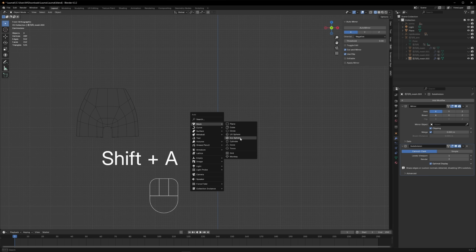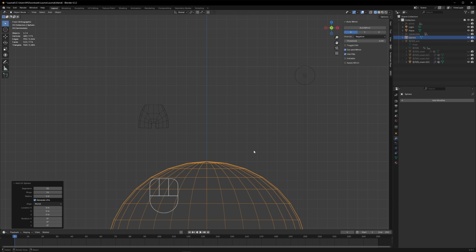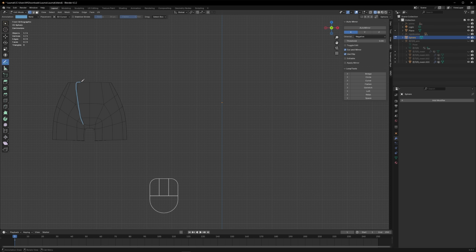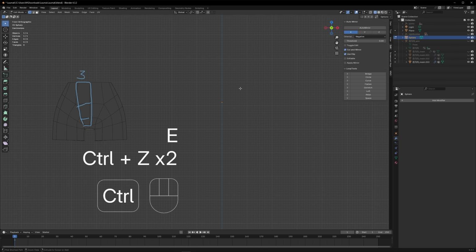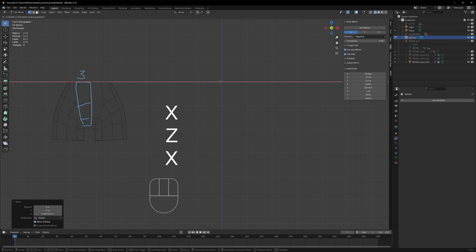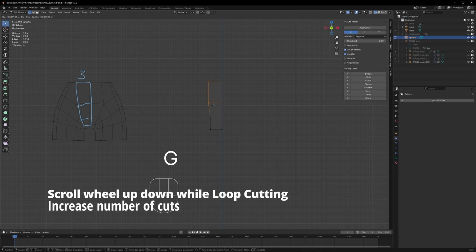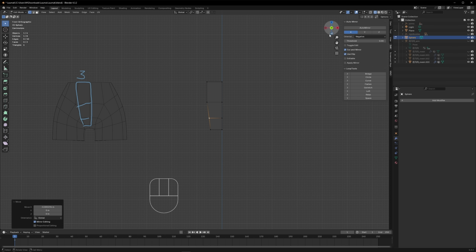Let's recreate this. Whenever I do a recreation, I break down the mesh into simple shapes and model the obvious parts first, and then it gets easier the more you go along, like a Sudoku puzzle. So if we start with the front crotch area, it's just a rectangle with 3 faces. So easily enough, we start with a single point, turn it into 2 points, and then extrude it downwards, then loop cut it twice.